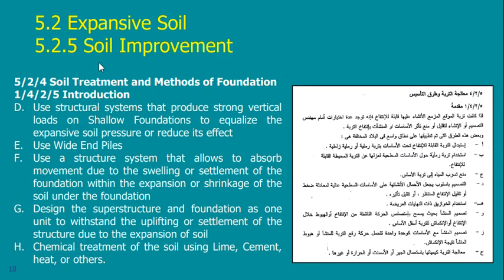Soil improvement, we have lots of ways. One of them is replacement, as we said. The other is to try to prevent water, though I do not believe in that. Whatever you do to try to prevent water from reaching, it may work for a while, but later in the future water will reach and it will be a problem. So I can use it only as an additional factor of safety, but not the main safety factor.